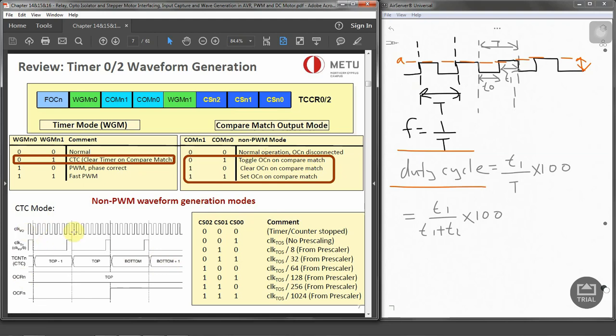First one, the waveform shows actually the system clock, let's say 8 megahertz. Then the second one is showing the pre-scaled clock. Now the third graph shows the TCNT count, and it updates on the falling edge of the pre-scaled clock. On our first pre-scaler pulse, the TCNT is TOP-1. So this is the first one. That was the start.